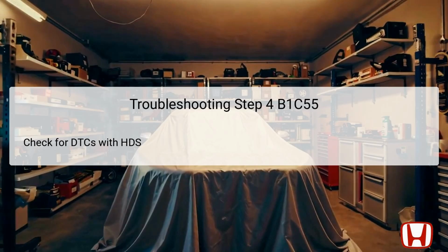On the other hand, if the DTC is not indicated, it might suggest an intermittent failure or that connections are okay at that moment. It is essential to have a diagnostic tool like the HDS, which enables precise readings and reliable error identification. If the DTC reappears, you will proceed to more in-depth checks as outlined in subsequent steps. Conversely, if the code does not appear, inspect the electrical connections to ensure there are no loose or corroded connections